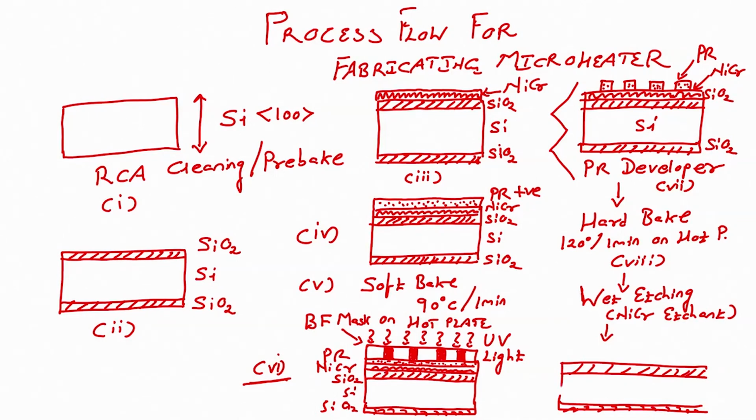I will have a wafer with what? I will have a wafer with nichrome on the area which was protected by photoresist, right. I will have a wafer with nichrome with the area protected by photoresist. Correct. After this what is the next step?